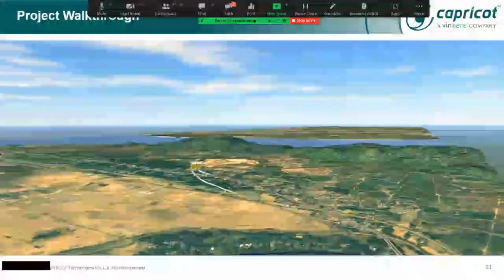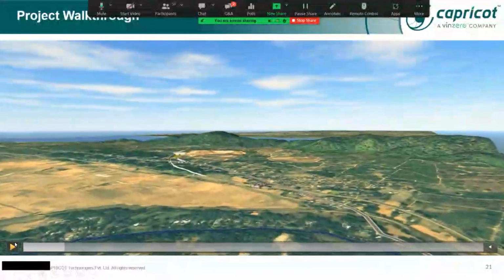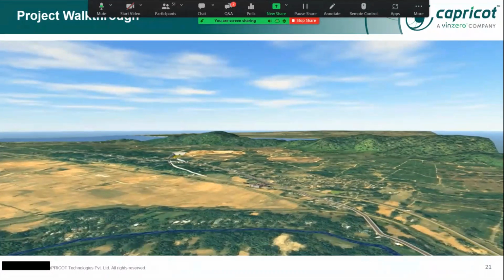I would like to add one more point. These days, digital survey is also in higher demand. Most government organizations are mandating drone and digitalization surveys. If I take an example of a particular industry, the mining sector, it has been mandated. The point cloud information, the aerial information which you receive, you can replace the preliminary survey data which has been captured by InfraWorks with that point cloud information you have.